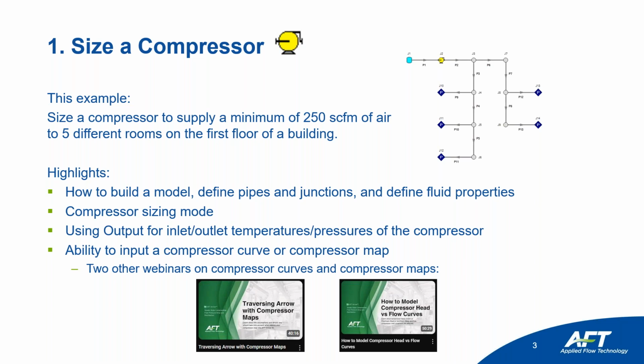We can look at inlet and outlet temperatures and pressures of the compressor, which you can then hand off to a manufacturer, and they can provide you with an appropriate compressor curve, compressor map. And after that, you can switch to those different modes that we went over in the compressor and model your system based on truly what is in your physical system.